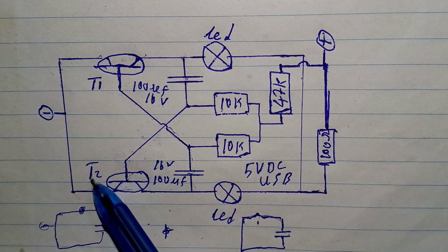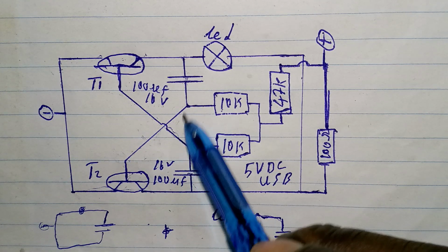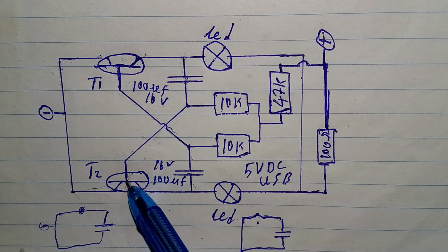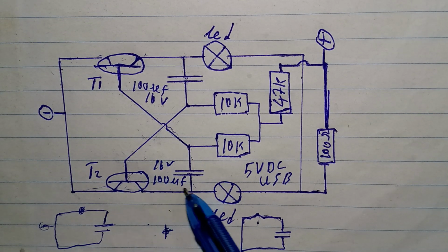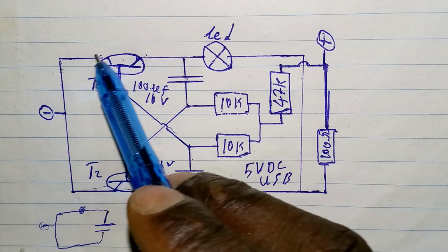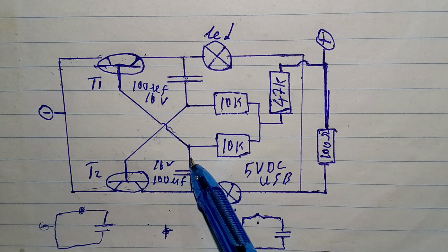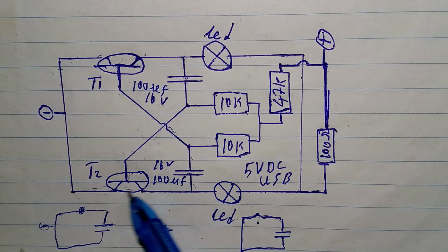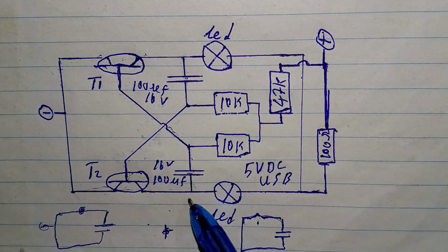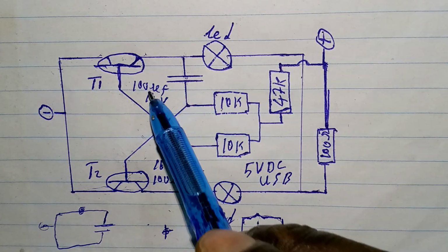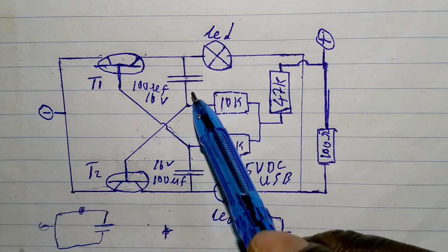If the voltage is moving this way, as this transistor is switched on, now the leads of this capacitor will be connected together. They are shorting together, but there is a resistance, so it is going to be slowly discharged. So that is exactly how a multivibrator circuit works.